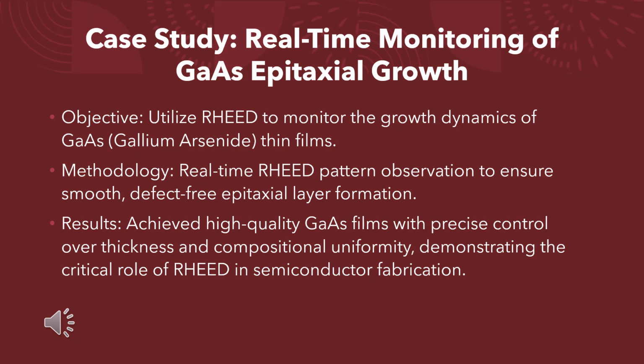Let's look at a case study that highlights the practical application of RHEED, real-time monitoring of gallium arsenide epitaxial growth. The objective here was to utilize RHEED to monitor the growth dynamics of gallium arsenide thin films. This involves real-time observation of RHEED patterns to ensure smooth, defect-free epitaxial layer formation. By analyzing the evolution of these patterns, we can optimize the growth parameters.